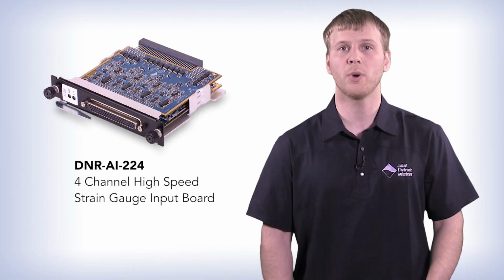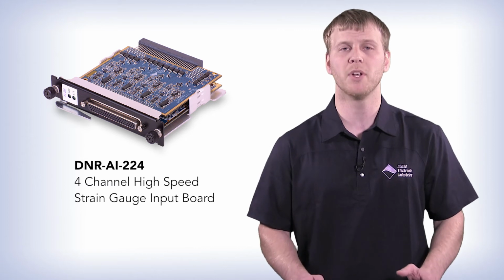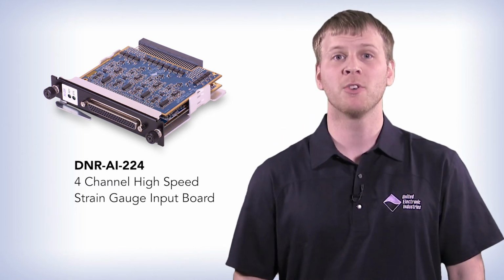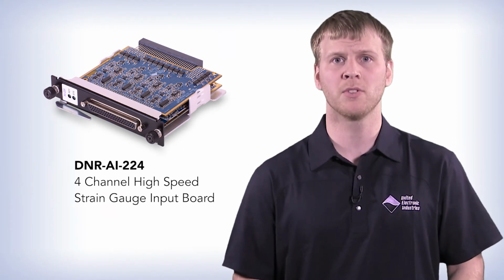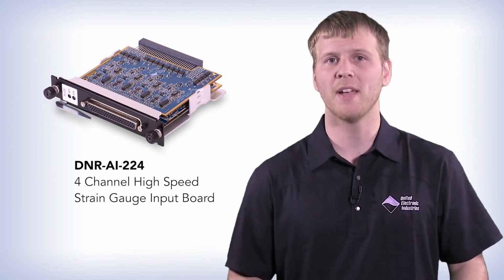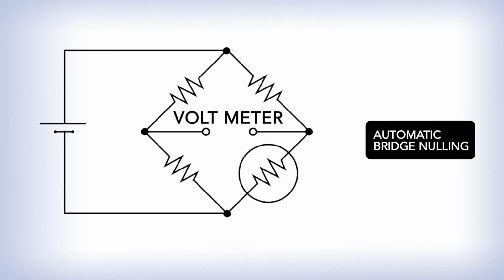UEI's AI-224 I/O board was specifically made to handle all 3 types of bridges. On board, there is a programmable excitation voltage, as well as completion resistors to make a full bridge when necessary. One of the unique features of this I/O board is the auto null capability. A strain gauge is hardly ever reading 0 strain at the beginning of a test. The auto null can null out this offset to give a near 0 strain starting point.